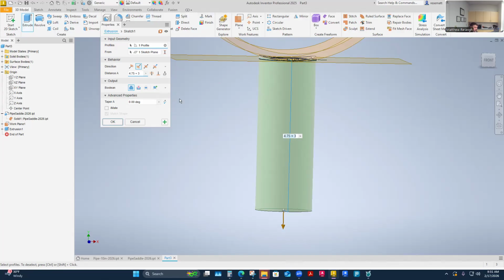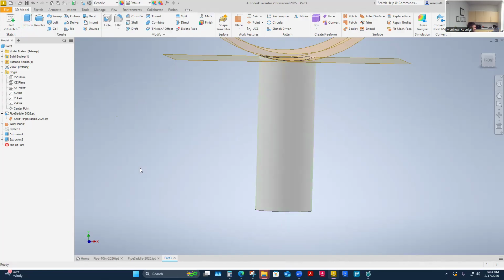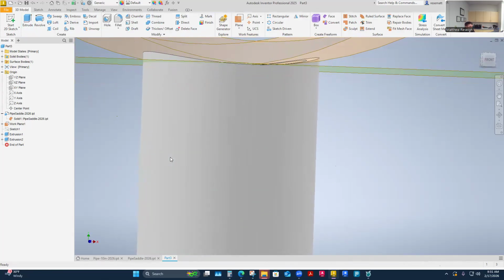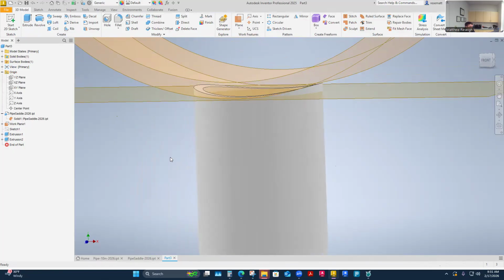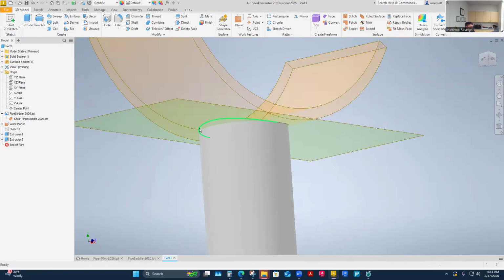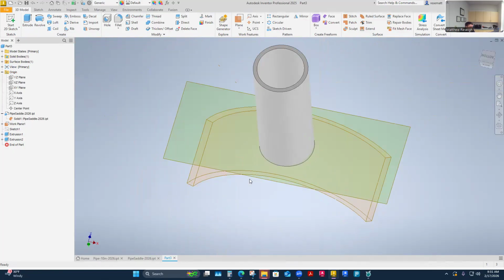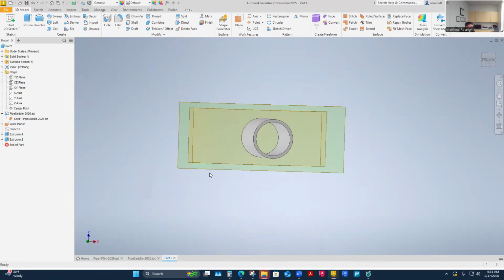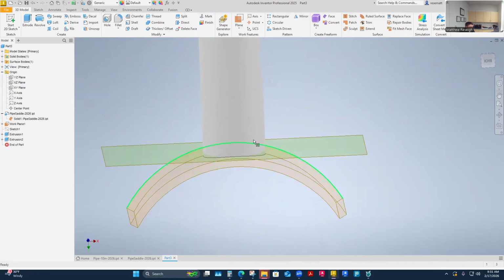I think it's value added in showing how to do multiple parts within one part. But okay, so I think this is it. This is how I need that to be. It's got a cope to it. Fits my saddle nicely. That's going to be a welded joint. I think it's a 3/16 fillet all the way around on that. Those two are going to weld together, probably in the shop first. Yep, just slap that thing over there.